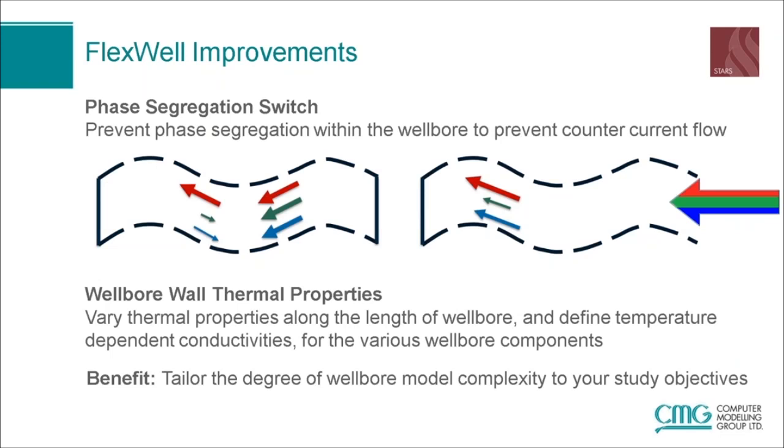For several years, STARS has had a transient wellbore model fully coupled to our flow simulator, and this is called FlexWell. So we've continued development of FlexWell this year by adding an ability for the user to disable or enable phase segregation occurring within the well. And we've added this because depending on the scope of the study, not all of the models that you're using may require the full wellbore treatment or the full phase segregation. And so with this new option, you can tailor the complexity of your wellbore model to the specific needs or outcomes that you want from your project or your study.